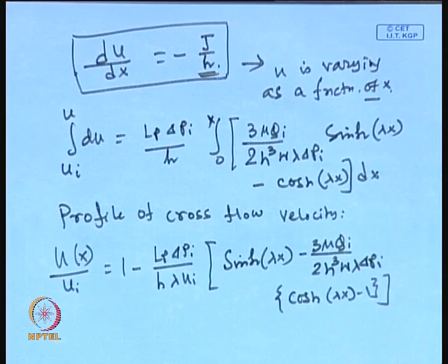Next, what have we done till now? We used the Navier-Stokes equation to get the governing equation of delta P. Then we did an overall material balance over a differential element and got the governing equation of Q or u. Now, if you do a species balance, or solute balance, over the differential element, you will get an expression of concentration. Let us do that.